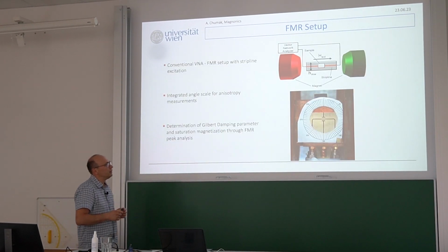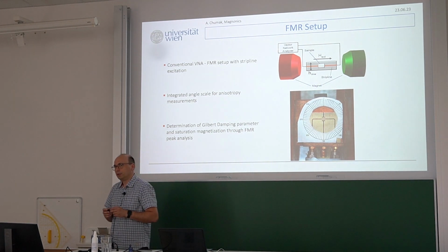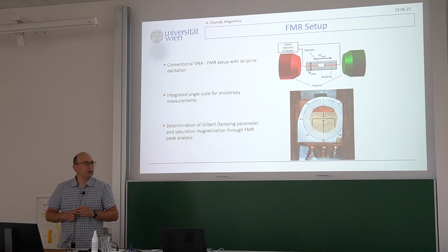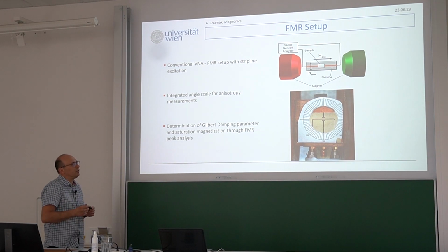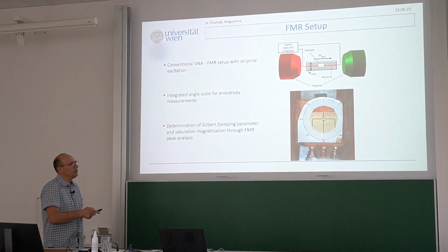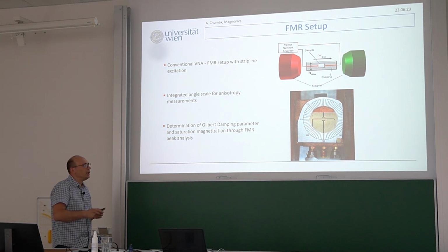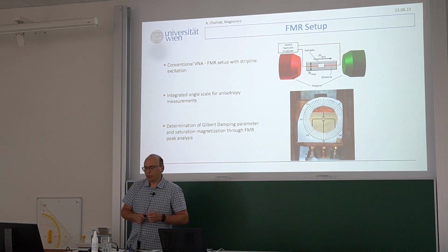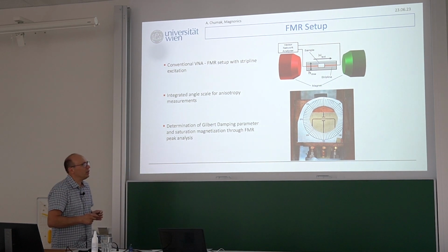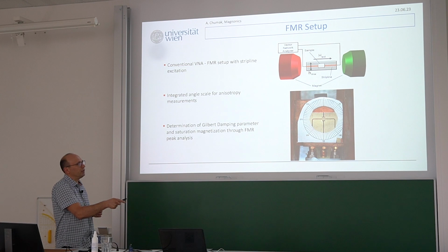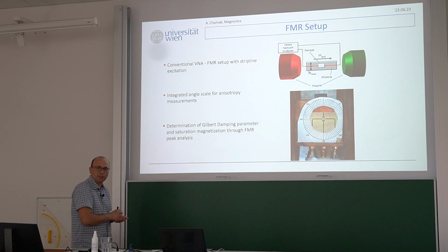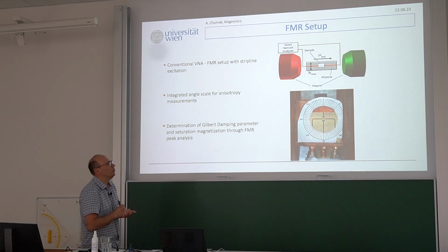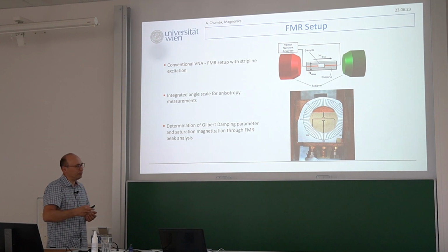On this PCB, the vertical antennas are just there to see at which angle I am. This is a section from another experiment. They are not in use in this one. What is used in this experiment is only this U-shaped antenna, and this is used for inverse spin Hall voltage measurements. So when you have yttrium iron garnet with platinum, you put it here, you connect the platinum here, we just put ground, and then using this SMA, you simply measure the DC voltage created by spin pumping and the inverse spin Hall effect. Yeah, so this is just here because we had such a sample.